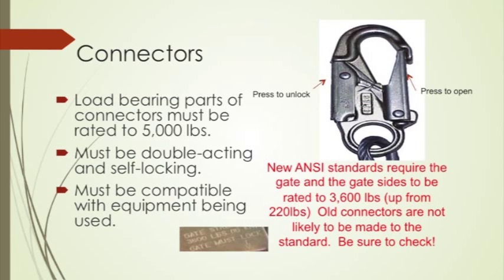Do not use connectors that are not intended for fall arrest. It is common for hoisting equipment and rigging carabiners to get mixed in with fall arrest gear. These have different purposes and cannot be used interchangeably.